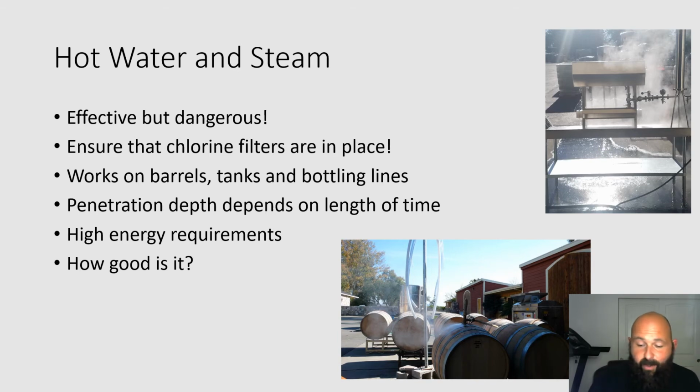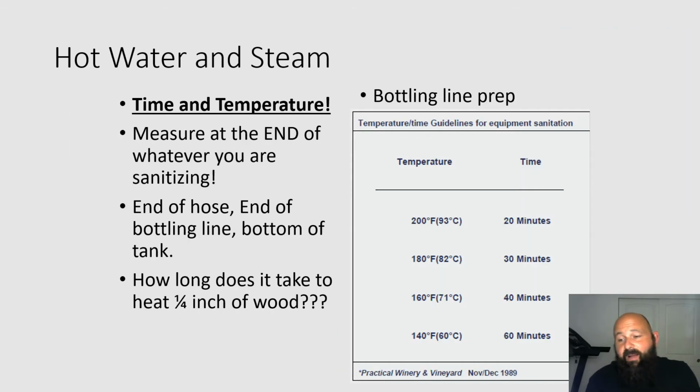How good is steam? Well, it's great, but you have to know your time and temperature. Time and temperature is absolutely everything. For bottling line prep, I've used this for as long as I've been in the industry. I think it's a fantastic guide from Practical Winery and Vineyard in 1989. So we're going back 30-plus years on this, but I think that if you want to be true in sanitation and pasteurization, which is how we pasteurize, with heat, whenever you're using steam, you need to measure time and temperature.